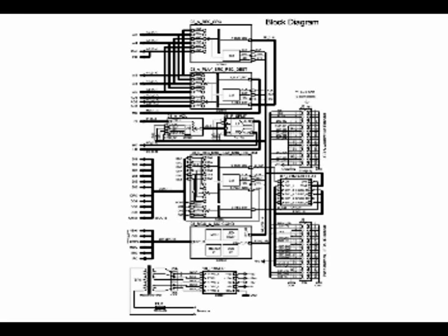As for the analog section, there are record and play source selectors and a record destination selector. The output from the record source selector goes to an SCMS defeat circuit. SCMS equals Serial Copy Management System, a copy protection scheme intended to limit digital copying to just one generation. But this will probably never be used now, since I've moved away from mini-discs since starting this Switchbox design.